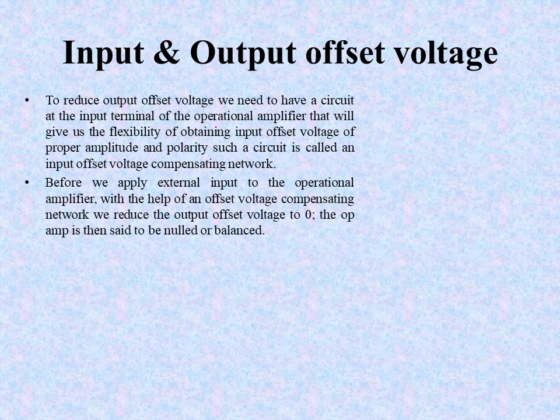At this position, when no external inputs are applied, and with the help of input circuitry we have nulled the output offset voltage, or output offset voltage is 0, then we say that the operational amplifier is in nulled position or balanced position.